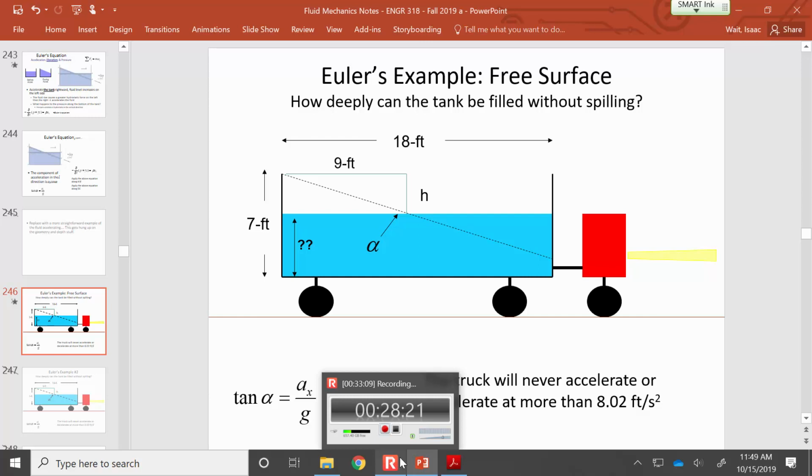So to predict delta P between 2 points, and that's how you'll mostly use it, but it's not just the delta P. It also defines the change in elevation. So more specifically, we'd say the delta P sub z, because inside Euler's equation is P plus gamma z. So it's also talking about how the liquid level responds to that local acceleration. You use Euler's equation to predict the change in piezometric pressure between 2 points.